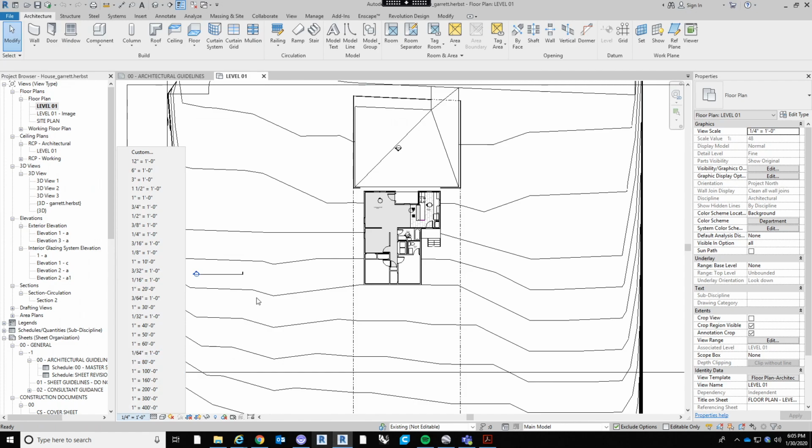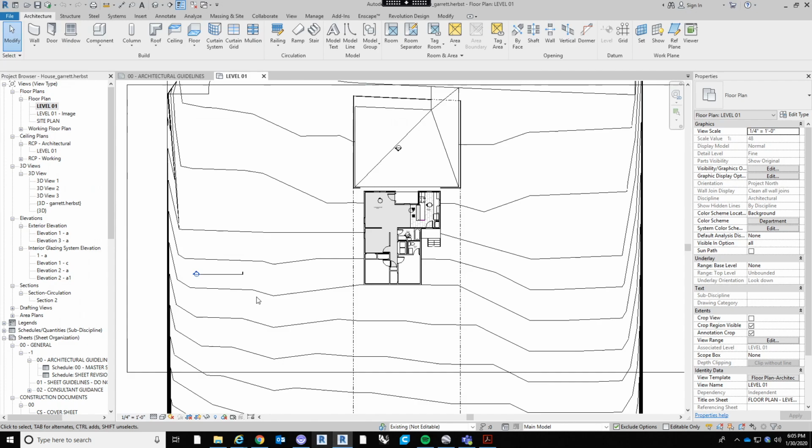Reason being, the level of detail and the size of those sheets are growing in real life. The scale of those drawings is getting larger or smaller, and all of the annotation devices are based around real measurements. So 3/32 inch tall text has to be 3/32 of an inch tall no matter what the scale of the drawing is. You have to be cognizant of that.